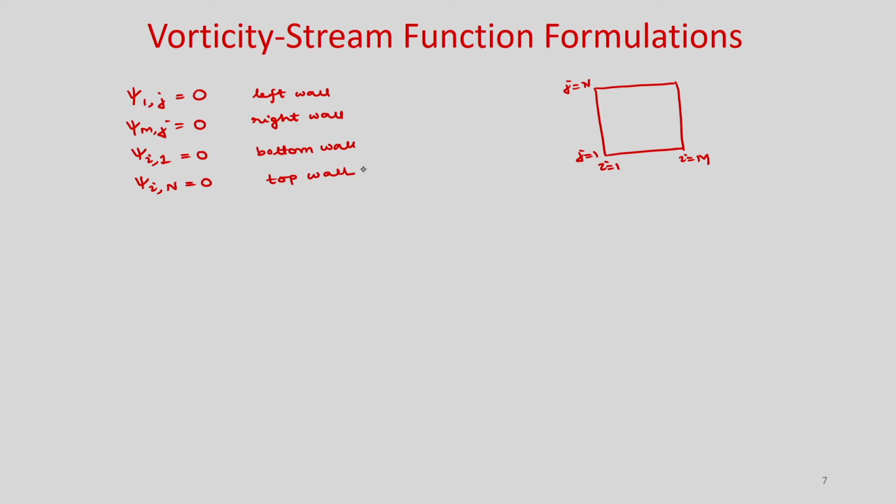So, these are the discretized boundary conditions for psi, and we have also shown the discretized boundary conditions for omega. You have the discretized equation for the interior points. With these boundary conditions, you can solve using some linear solver and you will get the values of psi and omega for this lid driven cavity problem.